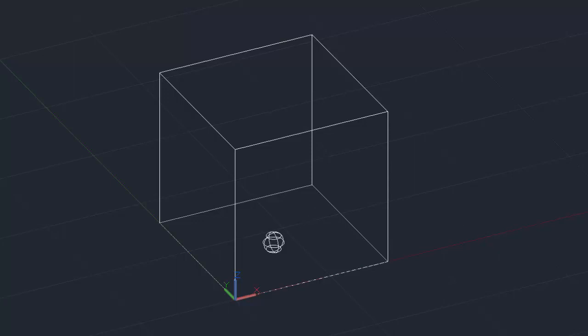Okay, so if we're looking at putting the 6 on next, just imagine from here, 1 across, 1 up, and then 4 in the Z to place it on the top surface. So you can look at the 4s. All this top plate will be 4s on the last command. It will be 1 across, 1 up, then 4. Next one will be 1 across, 2 up, and 4. Then 1 across, 3 up, then 4. Then it will be 3 across, 1 up, then 4, 3, 2, and 4, 3, 3, and 4.